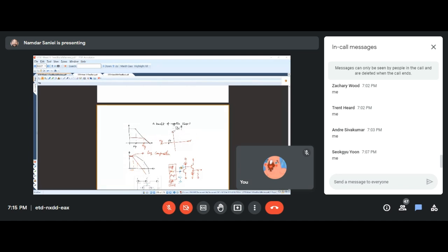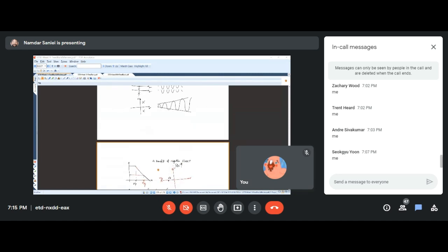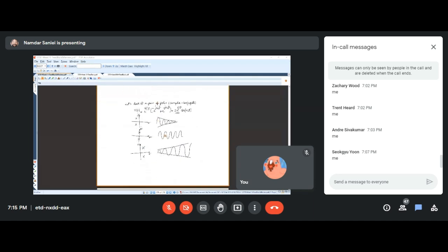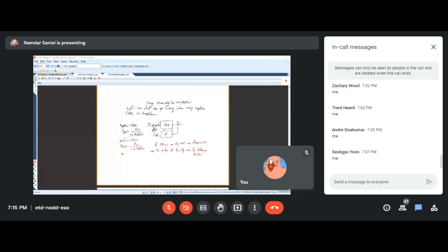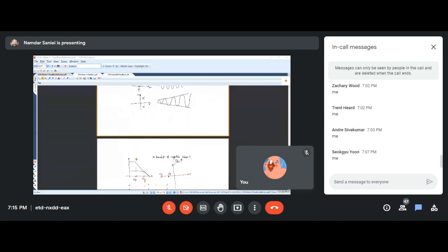So the effect of this capacitor is a filter that it makes with the dominant pole, and that dominant pole makes this multi-pole circuit look like a single pole circuit. And a single pole circuit does not go through this problem. This is for two poles. If you have a single pole, basically you have only decaying in time if you have any RC. Remember, RC was single pole.